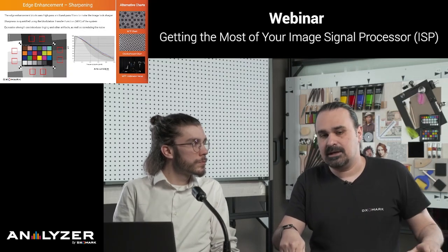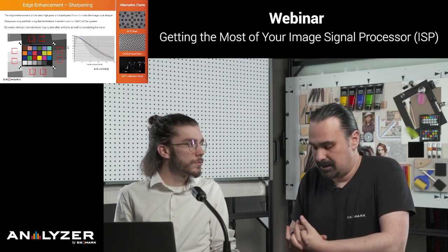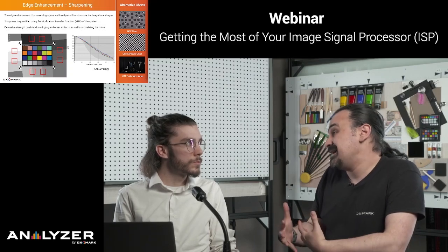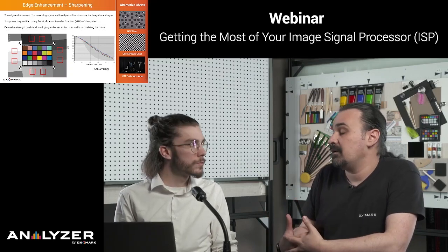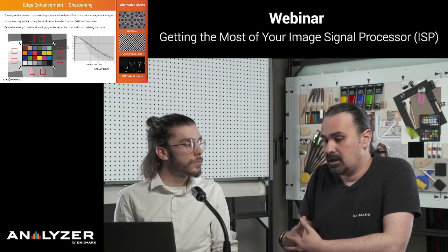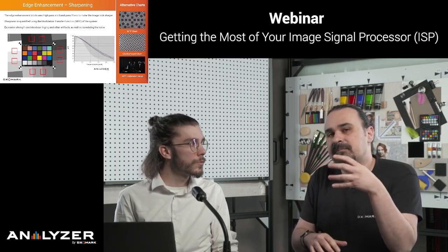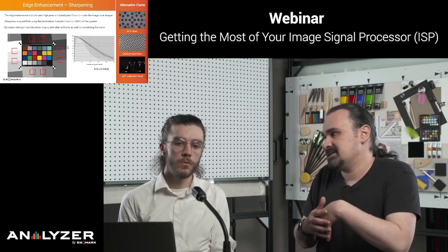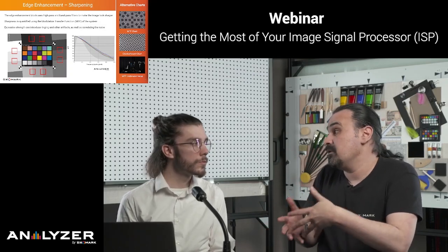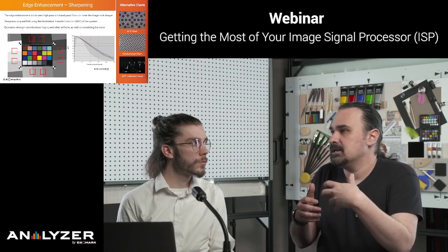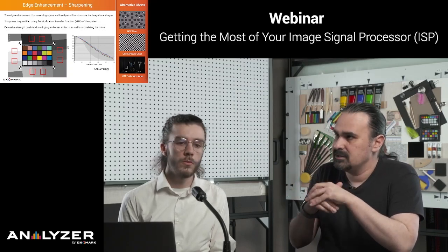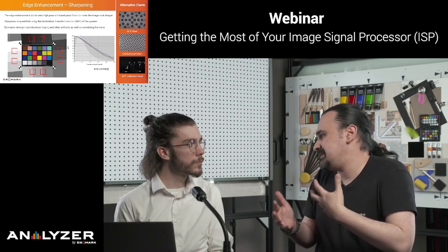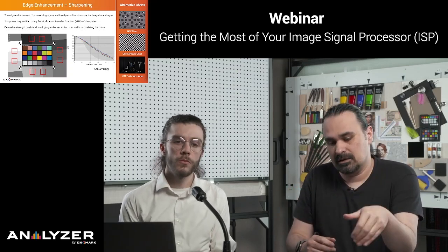And in fact, in many cases, if you have a complex pipeline, you wouldn't measure sharpness on a slanted edge at all. You would rather use a textured pattern like the one you find in our dead leaves target chart, because in theory, on a purely optical system like a DSLR, the result I get on the one or the other is exactly the same, but it's not the case if you have a complex pipeline. The textured pattern of the dead leaves chart is more representative of a real scene than a simple edge.